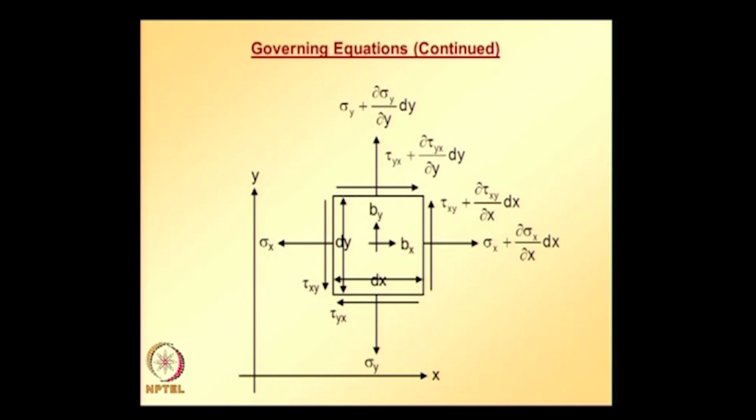And by writing equilibrium equations along x direction and y direction, that is considering equilibrium of forces in x and y directions acting on the differential element shown here, that is sigma F x is equal to 0, sigma F y is equal to 0, applying that condition.